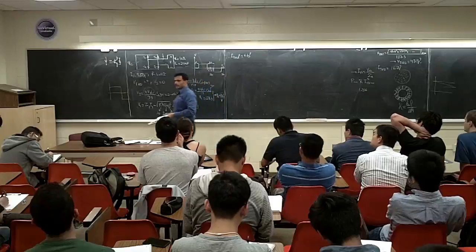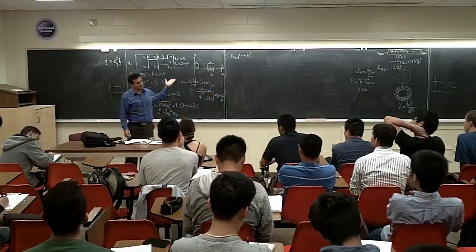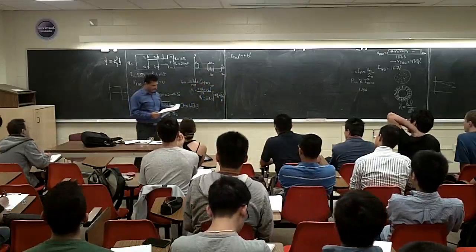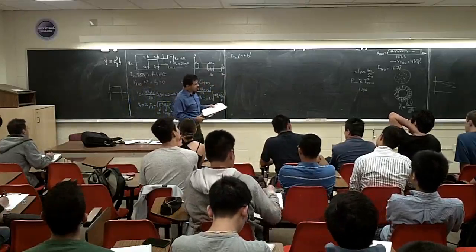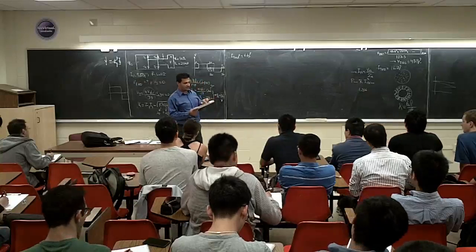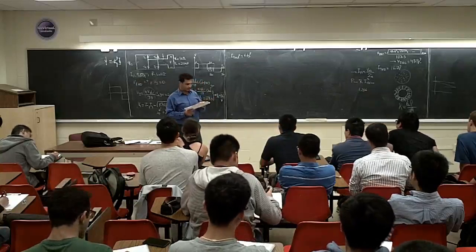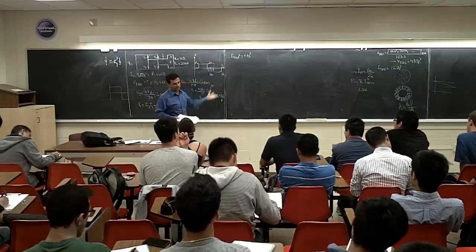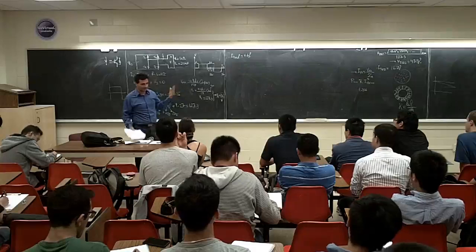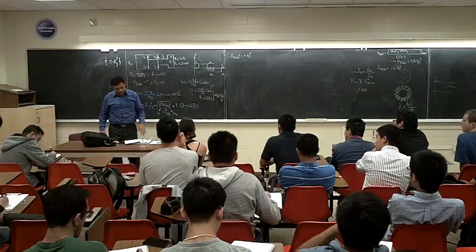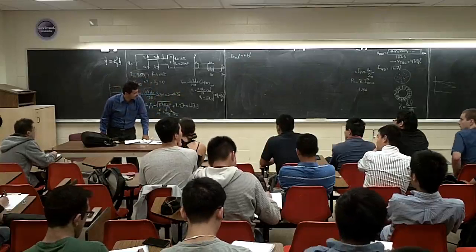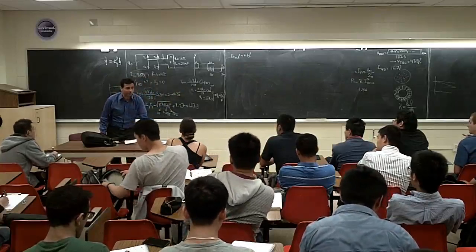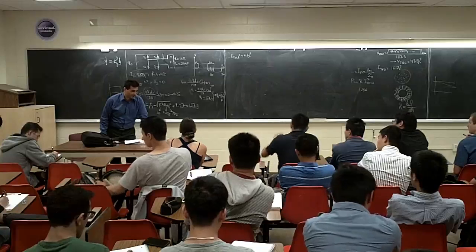So, can somebody tell me, if I want to eliminate the third, let me tell you the numbers here, for example. If you do this one, again, the rest is going to be untouched. The V5 is going to stay 25.5, and the V7 is from the table you have. Those ones are not going to change, because we actually brought up the DC. If you look at it, I would just get rid of the third harmonics, I improved 10% in my current THD.